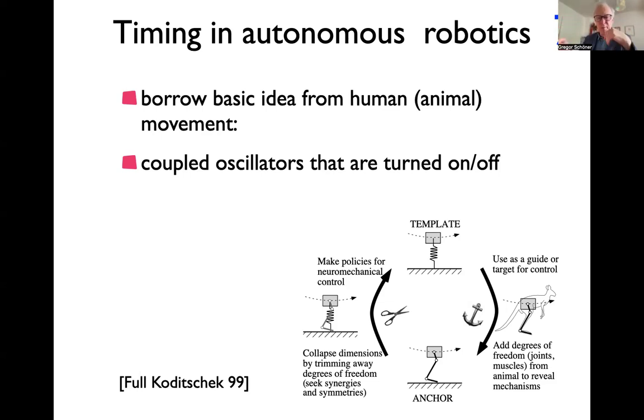Then it gets signals from the other oscillators, and that may accelerate or decelerate the limb oscillator you're looking at, so that it stays in sync with another limb that was maybe delayed or advanced because it hit terrain, let's say, advanced because the terrain was closer and it hit the ground earlier. And now the other limb also has to start its cycle earlier so that they stay in alternation. The details of that are complicated, but that's the basic notion.